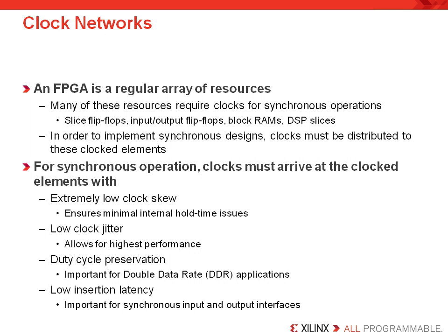The clock signal must also first be driven through a clock buffer onto a clock routing network. Any discrepancy between the clock and data delays can impact the maximum performance of the interface. Thus, we see there is a lot of challenge in building an optimal clock network for your FPGA design.